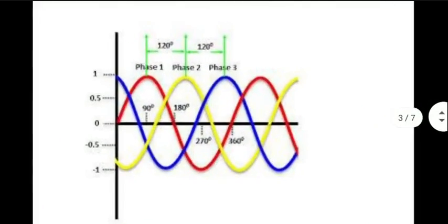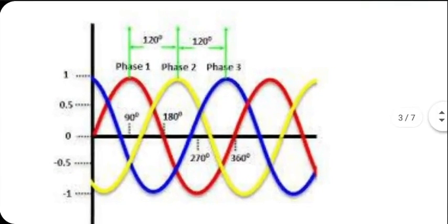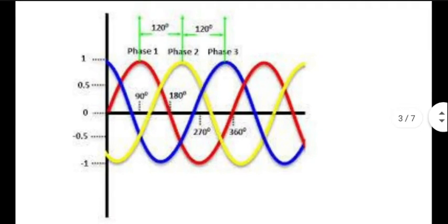Three-phase system. This is what they should look like. Three different voltages, all same waveform, same frequency, but they are starting at different instants of time with zero value. 120-degree phase shift progressively. Each voltage is given the name phase. Phase 1 means generator 1, phase 2 means generator 2, phase 3 means generator 3. There's progressive 120-degree phase shift. Here I am assuming plus 120-degree throughout, which is also okay, nothing wrong with it.